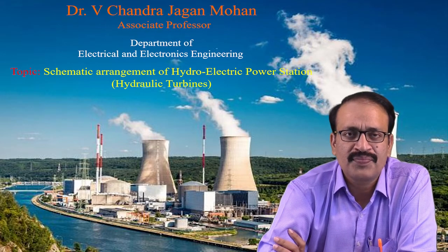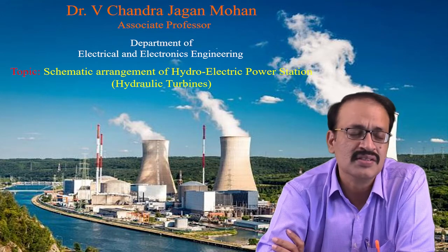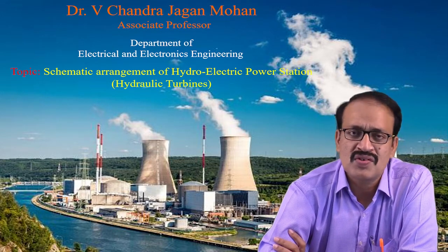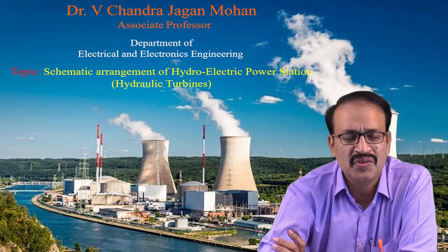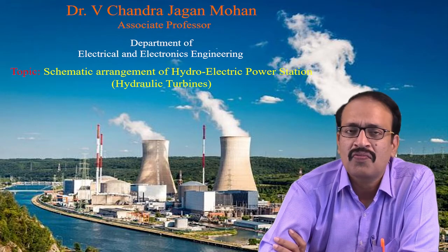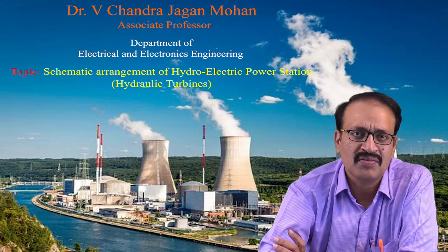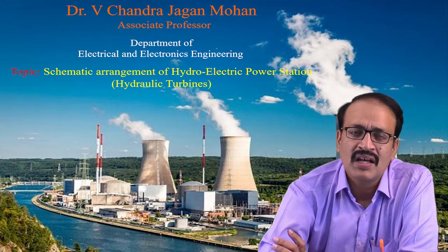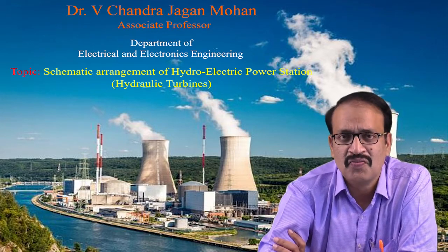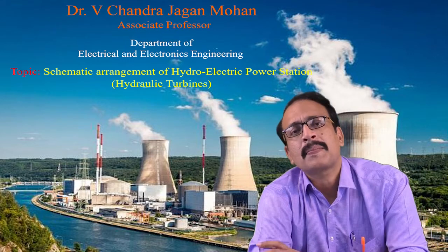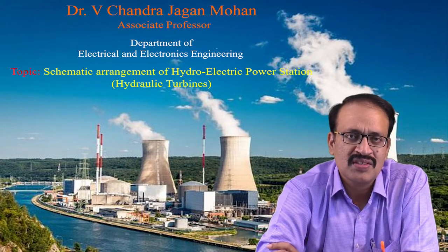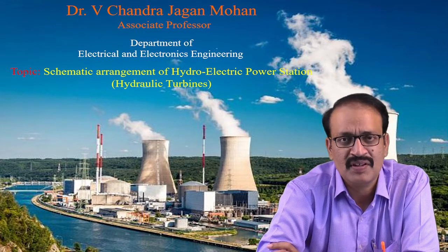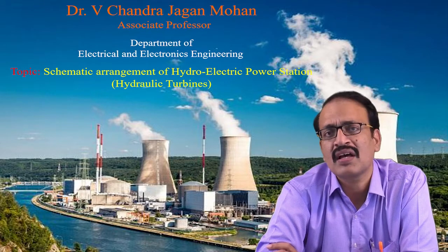In that flux, the armature or the rotor rotates, and an EMF is induced in the armature conductors, and from there we collect the electricity. So for generating electricity, we mainly need flux and the movement of the conductors. For that movement of the conductors, we need some external mechanical force. So there should be a rotation, and for this rotation we may use different methods.